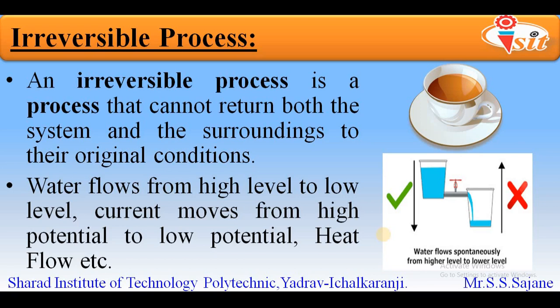The answer to this question is that when the water was coming from a higher level to lower level, at that time there was no work interaction, no external work applied to the system. When we bring this water back from lower level to higher level bucket, at that time we are using the pump which will consume energy. This causes a change in the system and the surrounding, and as a result of this, even though the water is brought back to the higher level bucket, we cannot call it a reversible process.